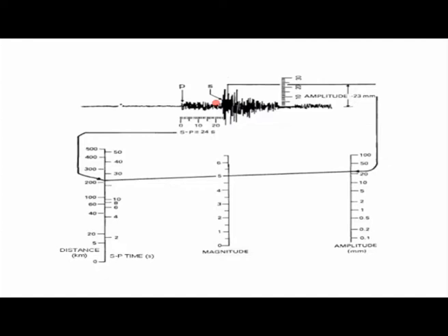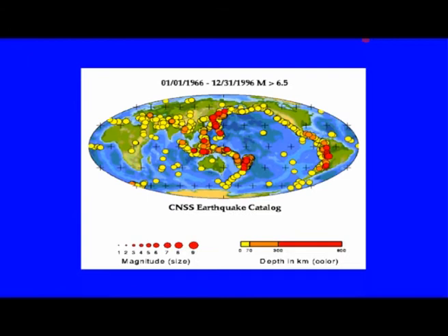That means you are standing at a particular point, sitting. If you can get the P wave and S wave and the difference of that, you can find out that the earthquake occurred at a certain radius, but you don't know where, it has occurred on the circumference of a circle. Now we can consider the different cases of earthquake at different positions. We can find out the distance, and the circle means what is the magnitude. I have taken this from USGS.